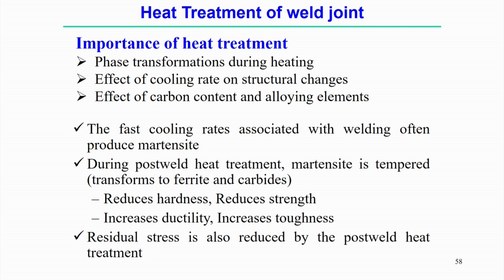The heat treatment modifies the microstructure basically, and that microstructure impacts the weld joint strength as well as ductility. So heat treatment is often associated with post weld treatment, to obtain good weld joint properties or to recover some amount of the ductility of the welded joint. The heat treatment is required.